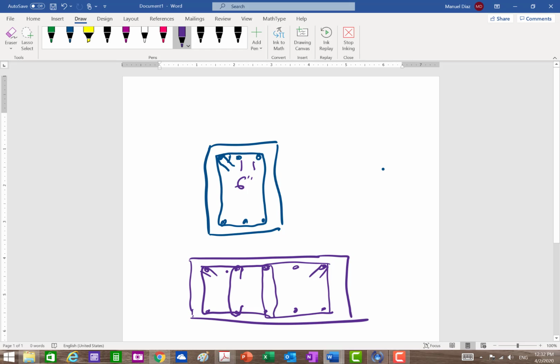There are different ways to arrange this, but you have to cover every bar. If this clear spacing is more than 6 inches, every bar has to have these ties. If it's less than 6 inches, you can skip 1. That's basically what they mean by that.